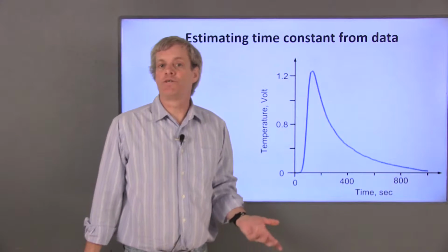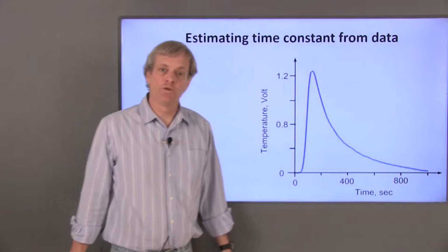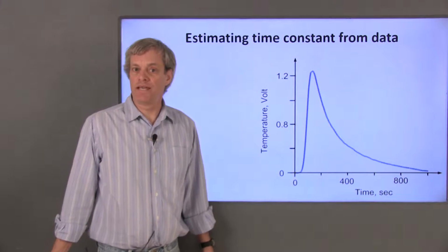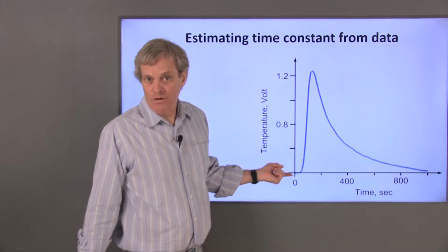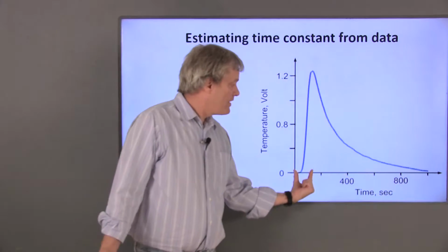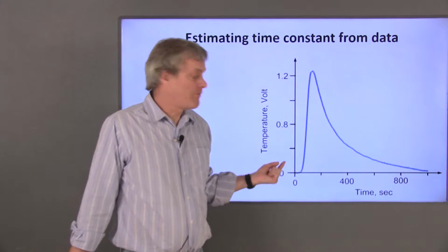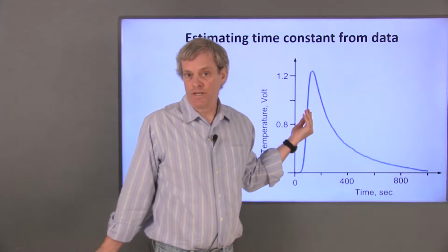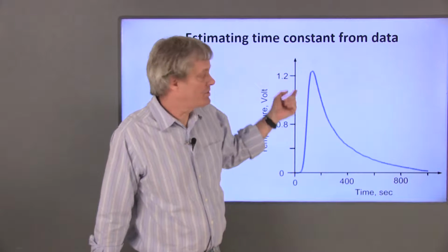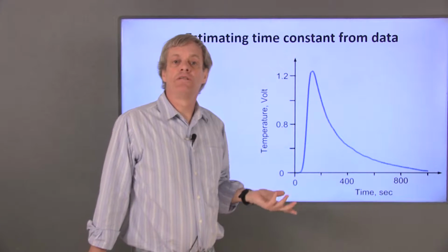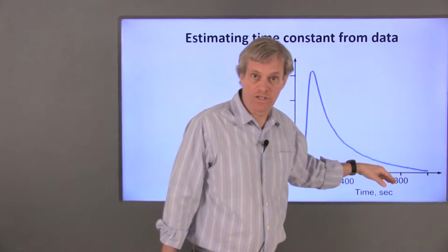The frying pan temperature is being measured by using a thermistor in a Wheatstone bridge. The output voltage from the bridge circuit is used to indicate temperature. Initially, at room temperature, the output voltage is 0, which is the operating point. During this time period, the heat under the pan has been turned on, the frying pan is warming up, and the voltage is increasing. Somewhere near this time, the pan is removed from the heat source and the pan starts to cool. During the cooling time, the pan is dissipating energy and the temperature decreases exponentially.